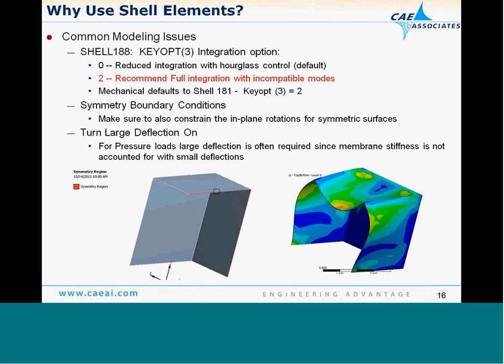Issues in terms of setting up or accessing our shell elements, again, depend on whether we specify to mesh with kept or dropped mid-side nodes, which will determine which element type ANSYS uses. With shells, ANSYS defaults to running with lower order shells, but if you keep the mid-side nodes, you can get higher order shells.